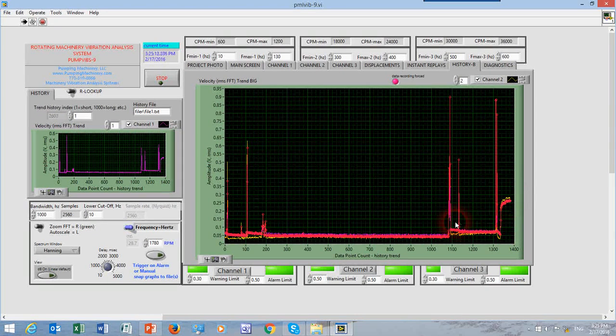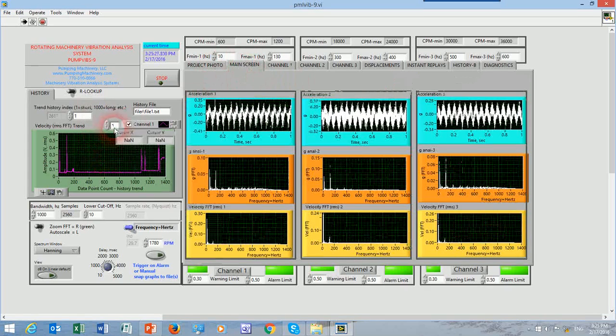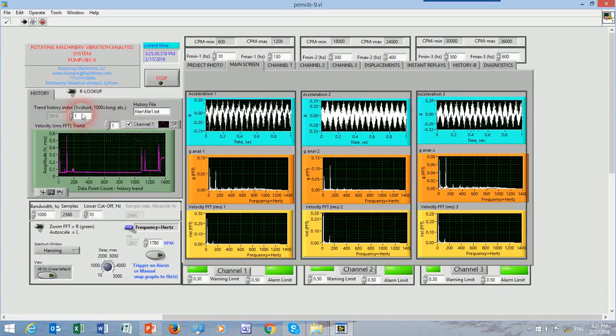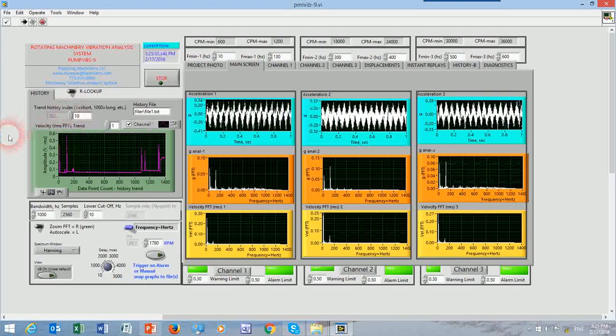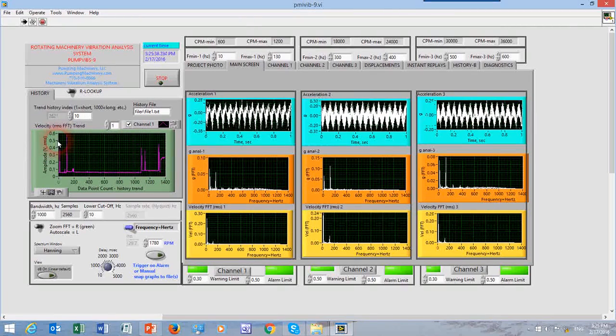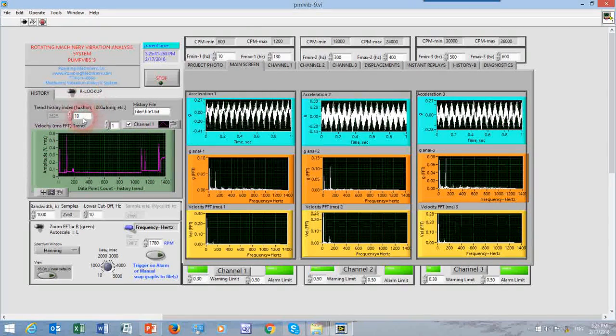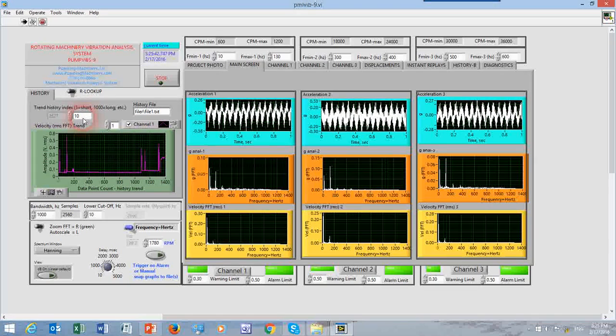The data is taken quite frequently, but if you want it not roughly a second or 2 apart, but maybe once a minute or once every 10 minutes, we can click here, where 1 I change to 10 or 100 or a larger number. 10 corresponds to approximately a minute apart. 100 will be roughly 10 times greater, 10 minutes apart.